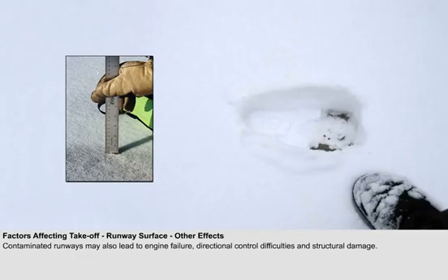It is therefore vital that the pilot be aware of the type of runway contamination, its depth, its extent, its effect on the braking, and of course its overall effect on the operation concerned. The recommendation by the United Kingdom CAA is that takeoff should not be attempted when the depth of water, wet snow, or slush is more than 15 millimeters. But check with the aeroplane flight manual in case it has a more severe restriction.